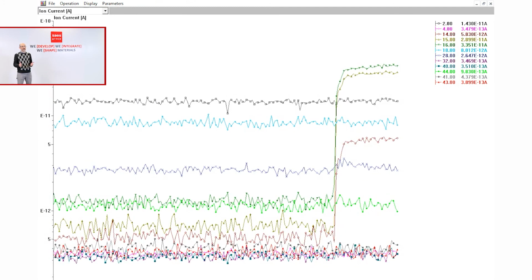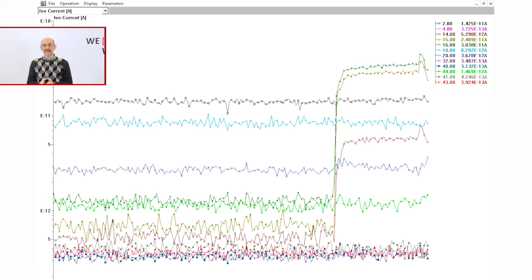Pressure soon stabilizes, and no signal from getterable gases like water, CO and CO2 changes significantly, since the pumping speed of the getter cartridge is by far higher than the one of the ion pump. When we turn on the ion pump again, pressure immediately drops. The system recovers the original pressures in a few tenths of seconds.